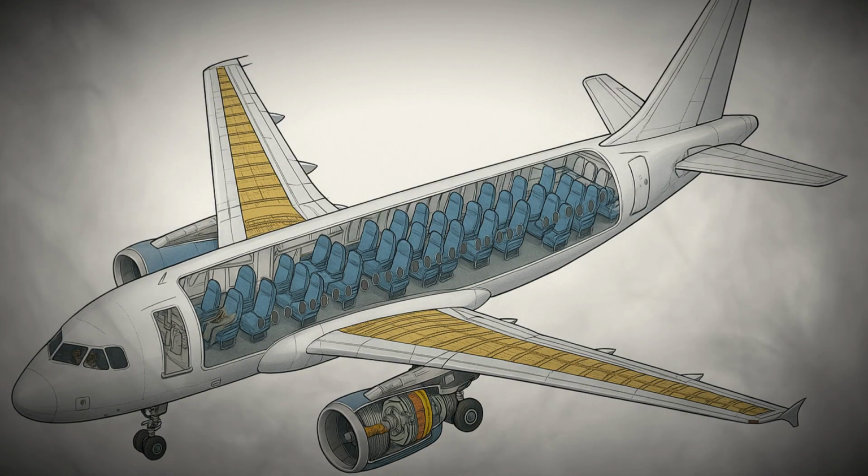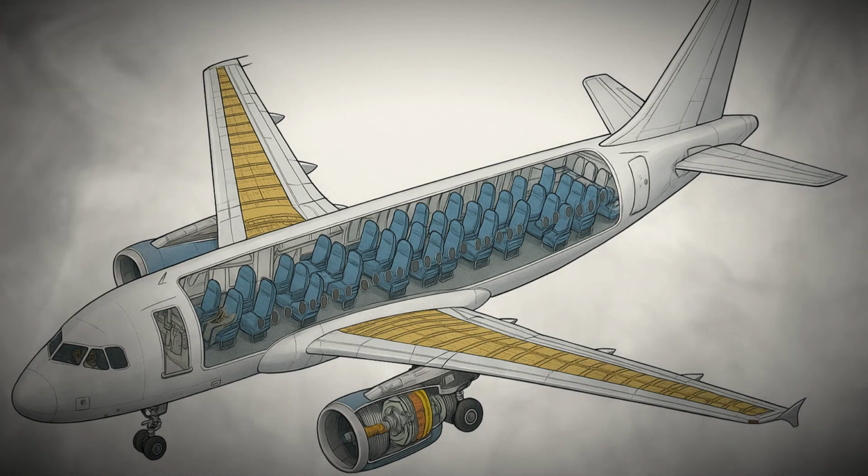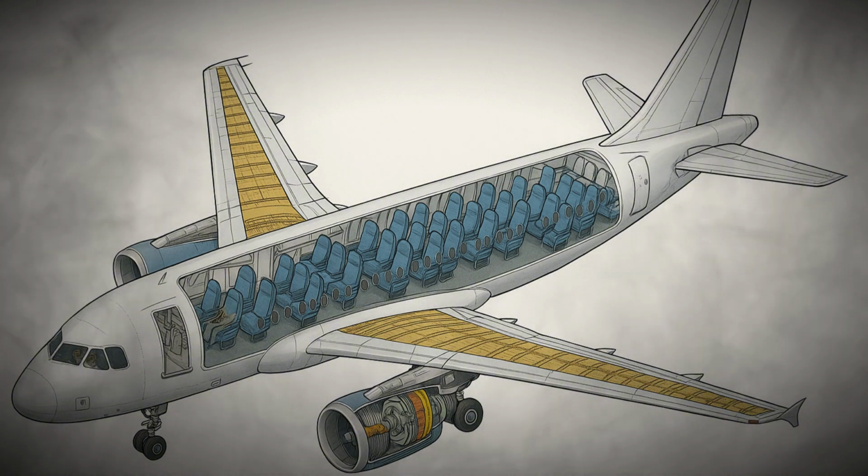In real flight operations, checklists are used systematically to confirm that every step, from configuring flaps and trim for takeoff to arming spoilers for landing, is completed properly. The critical nature of these phases is reflected in accident statistics, which show that most aviation accidents occur during takeoff and landing rather than cruising.